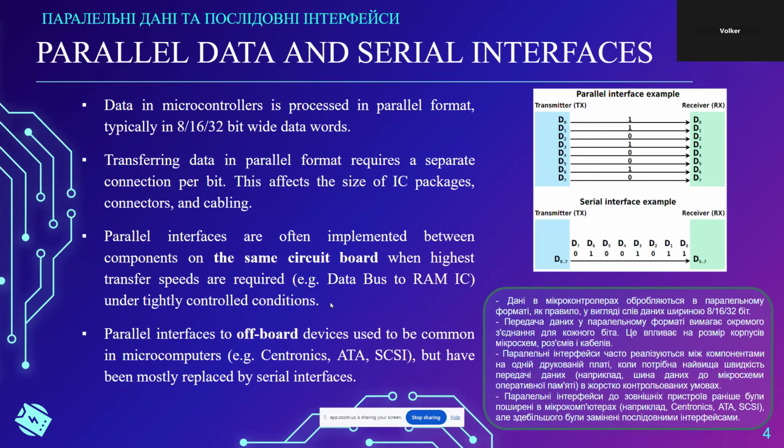So basically at those speeds, even picoseconds count. If you were to look at a circuit board for PCs, for example, you will notice that some of the traces will make weird, unnecessary curves, turns. This is done for guaranteeing that all signals arrive at exactly the same time.